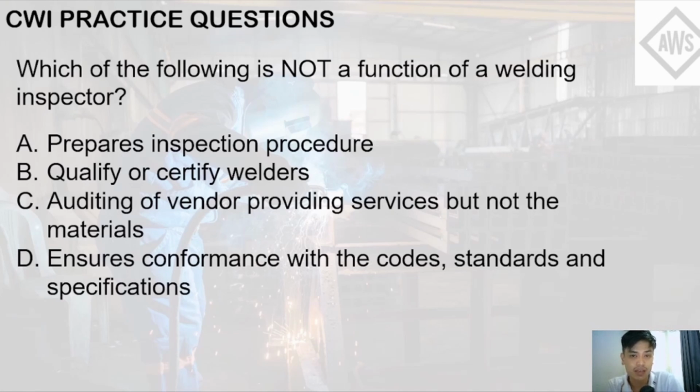The documents like MTRs, mill certificates, the factory standards used for the production of the base metal, and the testing or the destructive testing used prior to shipment should also be analyzed and scrutinized by the welding inspector.